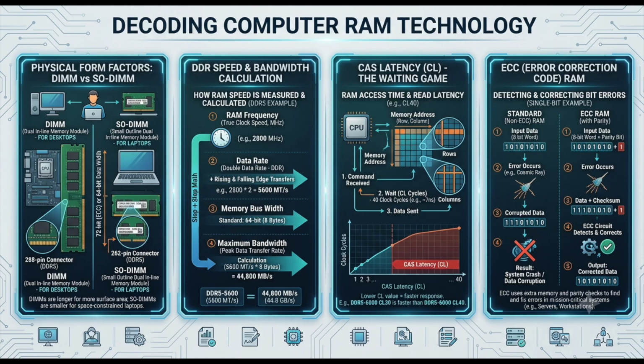If a single data bit flips, it won't just trigger one parity error, it will trigger a highly specific combination of parity errors across those overlapping groups. Wow. The memory controller looks at that unique combination of failed checks, and the mathematical intersection points to the exact specific coordinate of the corrupted bit. Because bits can only be a 1 or a 0. Exactly. If the controller knows exactly which bit is wrong, it simply reverses it. The error is detected, mathematically isolated, and corrected in real time without the processor ever even knowing it happened.